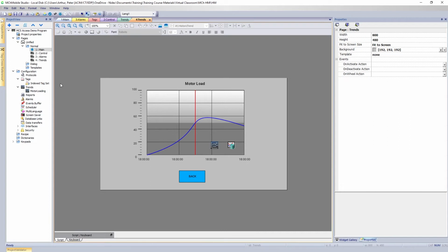The reason why I'm asking this is I work with a couple of manufacturers, like Allen-Bradley, Pinor, or Wago. So you'll be designing a screen for 10 inches or 7 inches, and then suddenly the customer needs it to be 10 inches instead of 7. So you have to go back and change everything on the screen. Some of them supply a feature which stretches the screen, and it will adjust all the dimensions to match the new dimensions. That's easier than taking each item on the screen and changing it. That's why I asked. I think here.